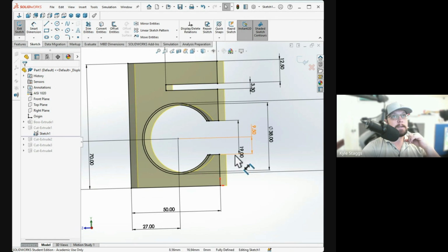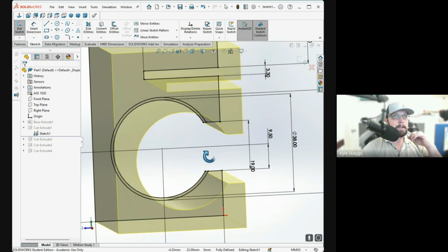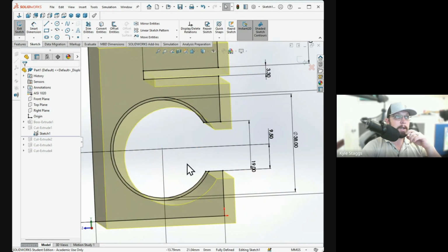Then I set the lines 19 millimeters apart. I made them horizontal, and therefore perpendicular to the rectangle. Then I positioned them by dimensions, 19 apart and one side 19 divided by 2 to put it in the center. That's how I set up the C shape.